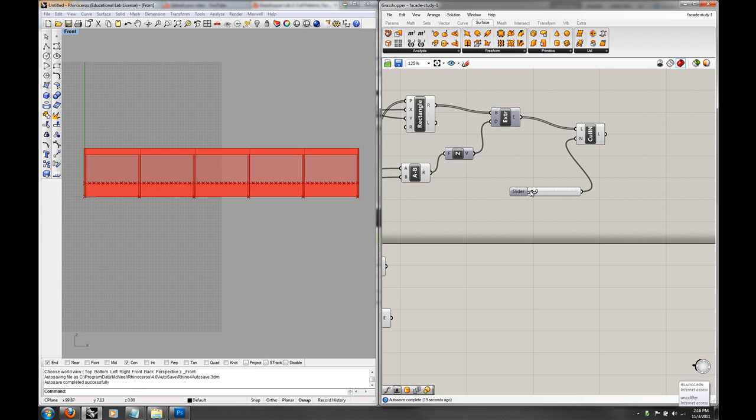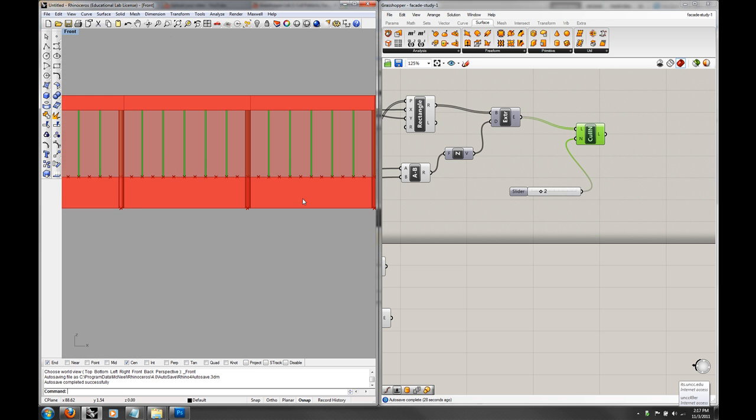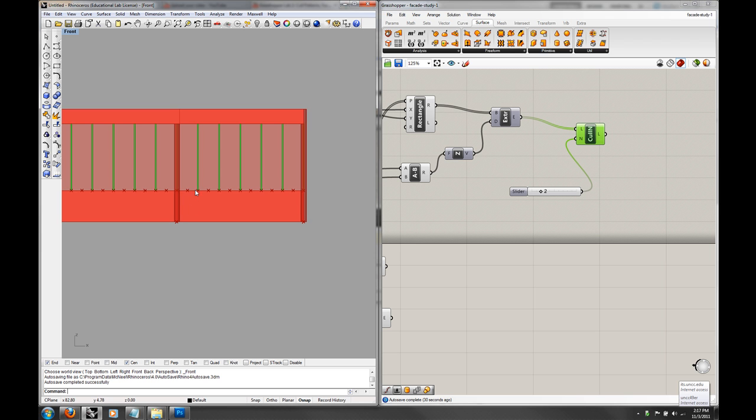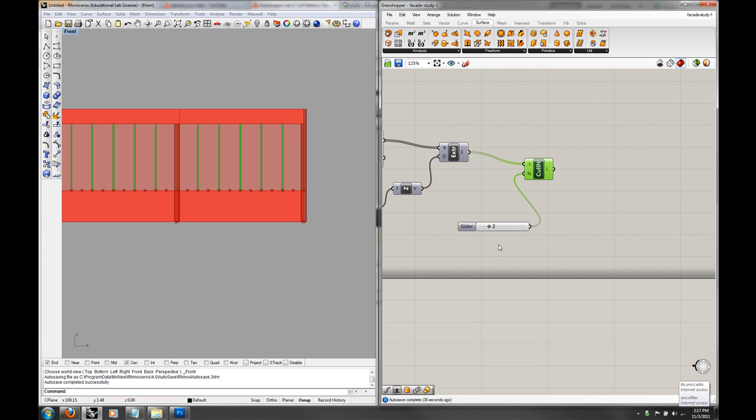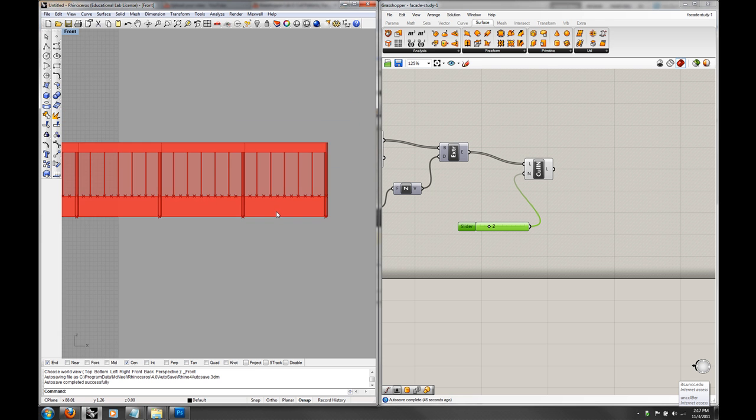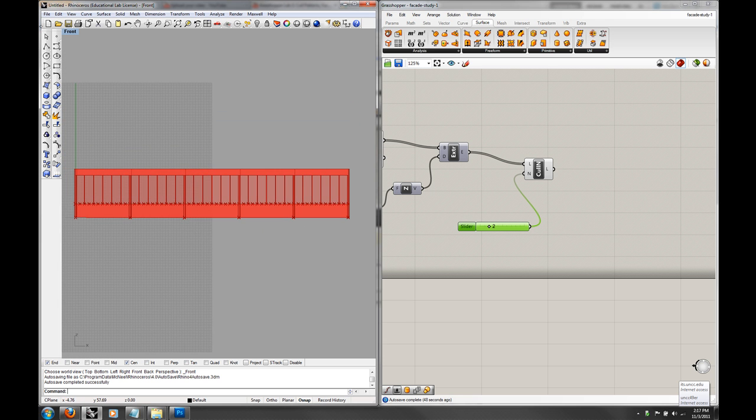And if we know that there are so many per bay, then we could actually do something like a true false mask. So if we know that there's 1, 2, 3, 4, 5, 6, 7, 8, 9, 10, 11, so we know there's 11 things, we could do a pattern that repeats every 11 using a cull pattern. Okay, so there are different ways of experimenting with this.